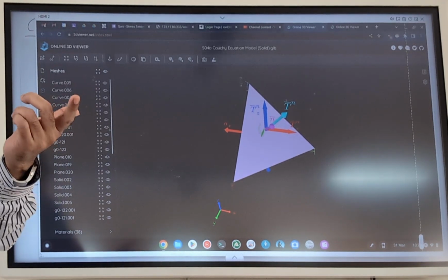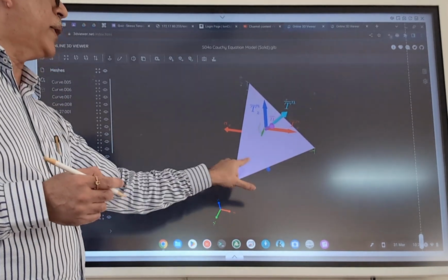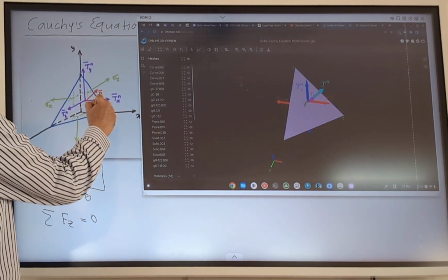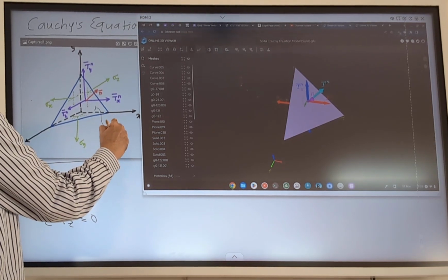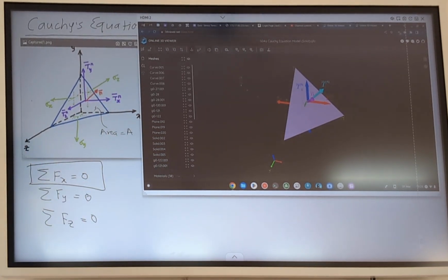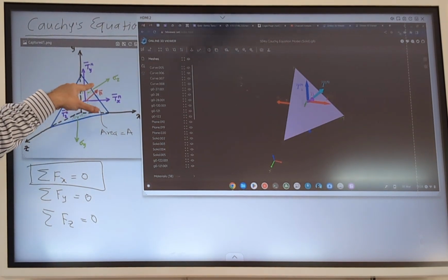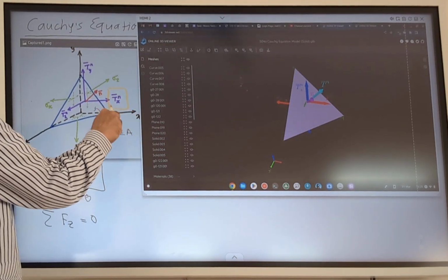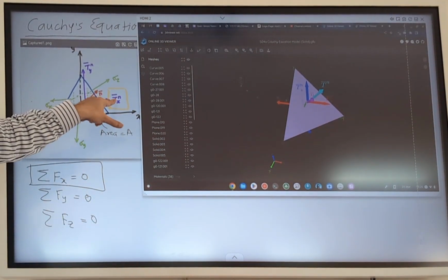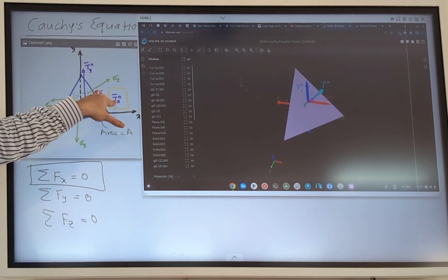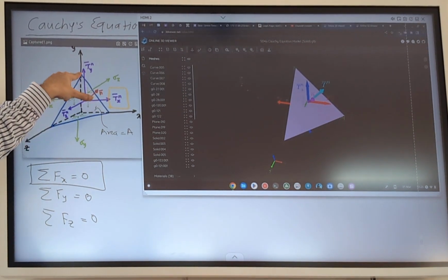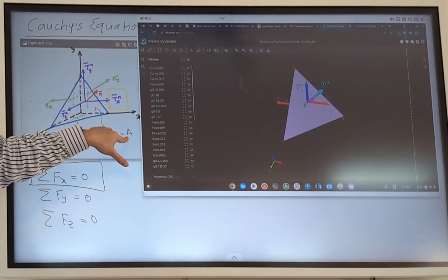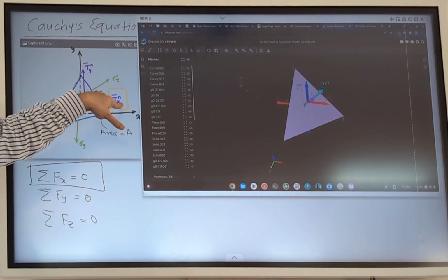So if Tnx is the magnitude, and let's say the area of this particular face is A, I will call the area of this face equal to A. Because of the x component, here we are talking about this Tnx bar. So what will be the force in the x direction because of Tnx? This traction vector is acting on a triangular face whose area is equal to A. The magnitude of traction is Tnx.